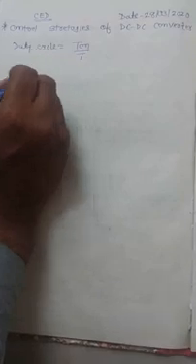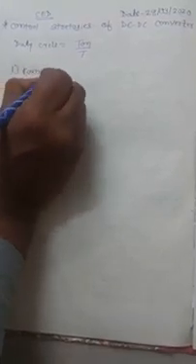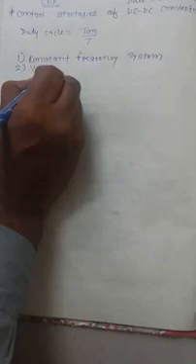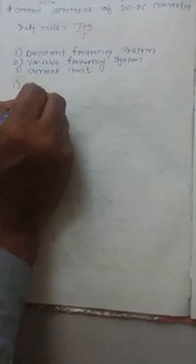Control of the DC motor has three methods. First is pulse width modulation, that means a constant frequency system. Second is the variable frequency system, and third is current limit. So, constant frequency system.